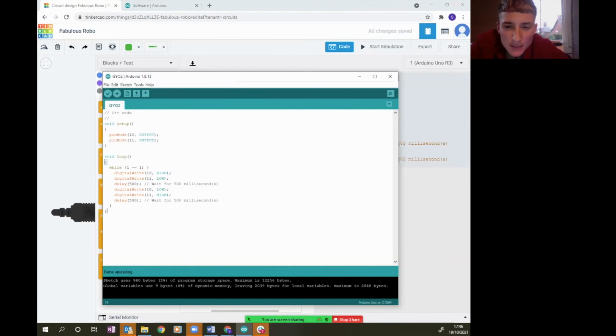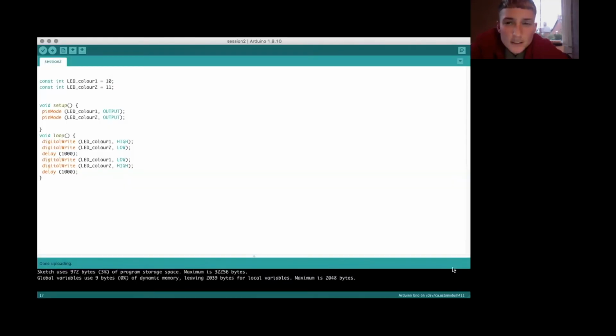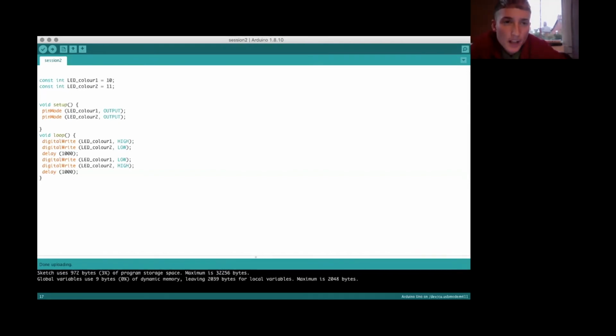Should I share my screen? Yeah, hang on. Okay, so everybody see that? So if for any reason it's not uploading to the board, it might have an error message at the bottom that says, I think it's something can't upload. It might be because we haven't selected the Arduino board on our port.